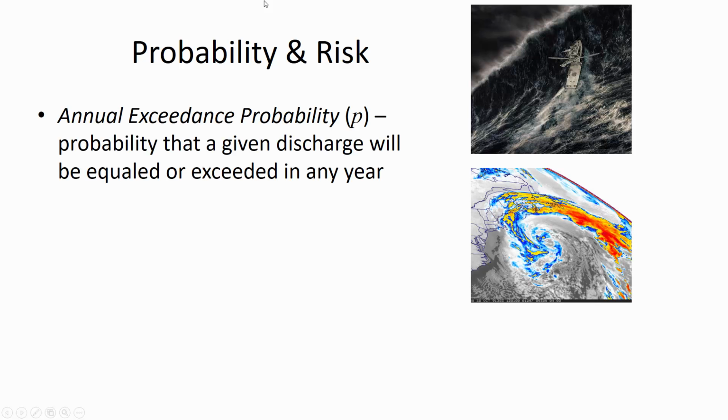And so when we think about probability, it's a really important part of hydrology, and then by extension an important part of engineering, because the flow rates that we design for are going to accommodate flows that happen maybe only occasionally. In the last class period we talked about how you're designing a sewer to handle the flows when the city's all completely built out and some extreme condition like really wet weather or a rare event.